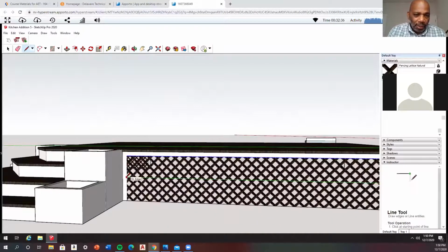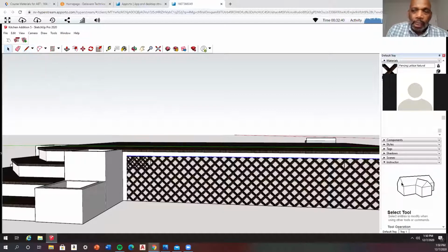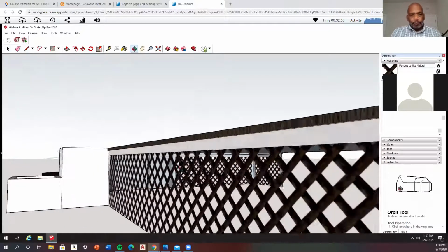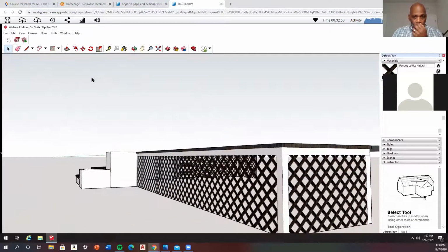We might make it less than that. Let's see what it looks like. I tell you what, don't make it a 2x12. Make it a 2x10, so just come down 8 inches. And you're going to do that all around the edge of that deck, except for when you get to the stairs, of course.